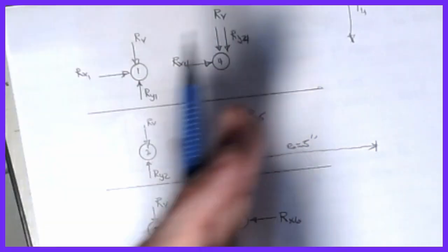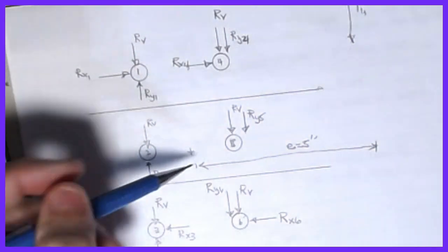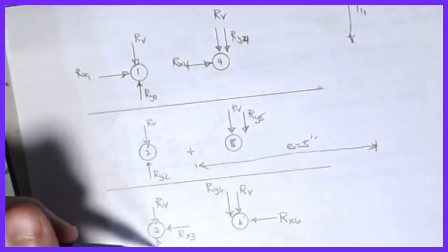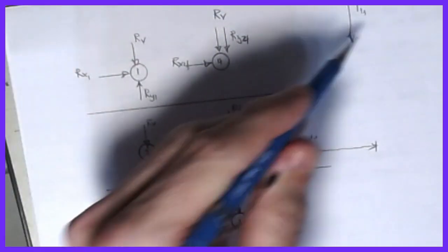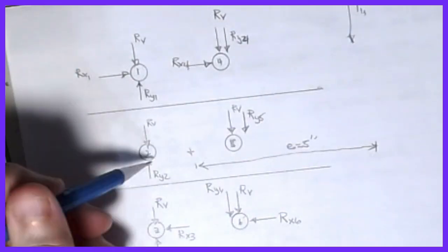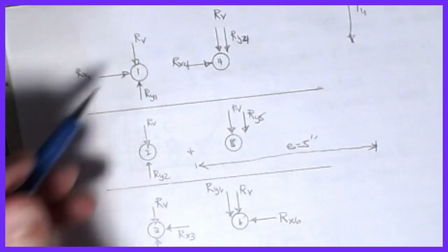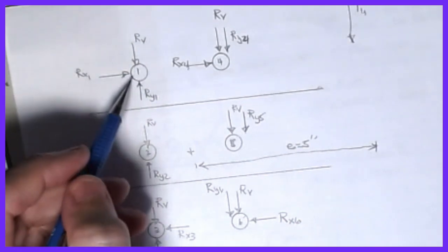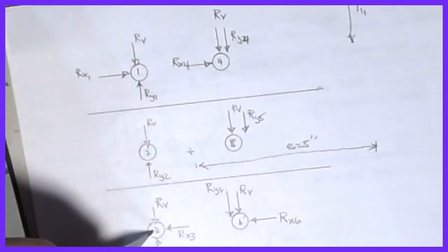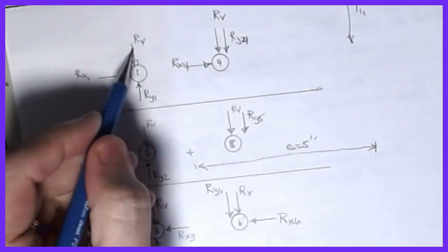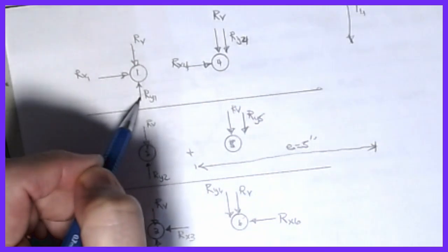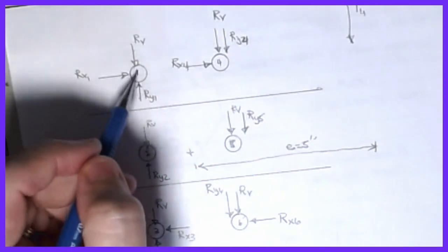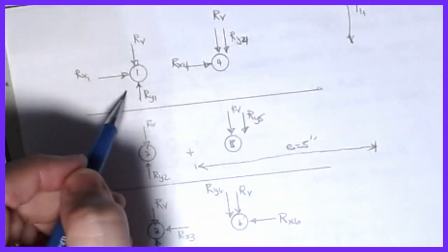Okay, and then you'll notice that to the left of the centroid, my RY, which is from the moment, the eccentricity due to that eccentric force, they're all acting up on this side. Okay, and so you can see that for this case, typically these bolts will have a smaller magnitude because the direct shear and the eccentric shear portion of this are fighting each other and actually reducing the overall quantity, and that reduces the magnitude of this force.